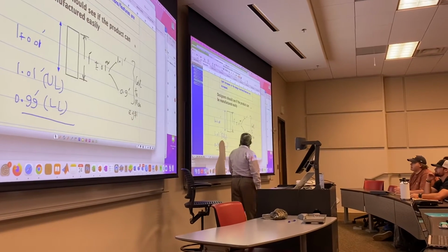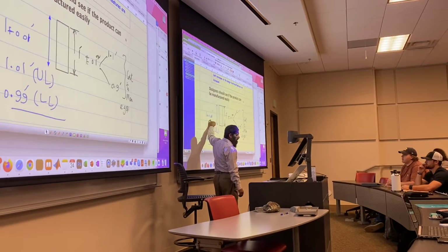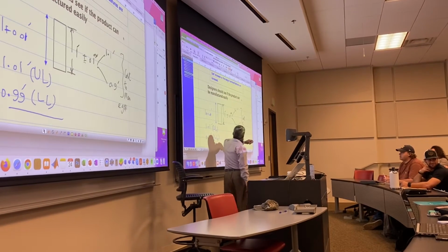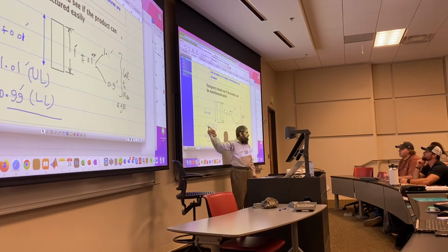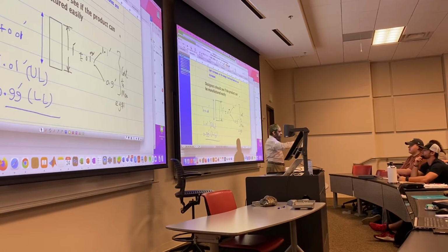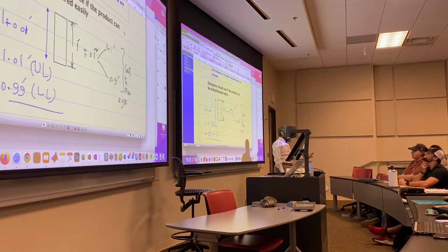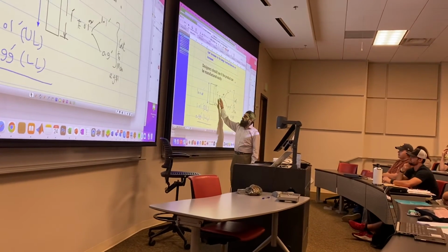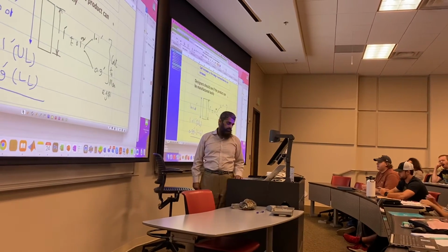So let me tell you. If you give this loose tolerance as compared to 1/100th of an inch, okay, 1/100th of an inch is difficult to manufacture. The person will use the tools many times to make a finished cut to generate this much tolerance. So it is better to give a loose tolerance if you can perform the same functionality, rather than giving a very tight tolerance and increasing the manufacturing cost, because tooling is required to have this much precision cut. So it's a good practice to have a loose tolerance to reduce the cost of manufacturing.